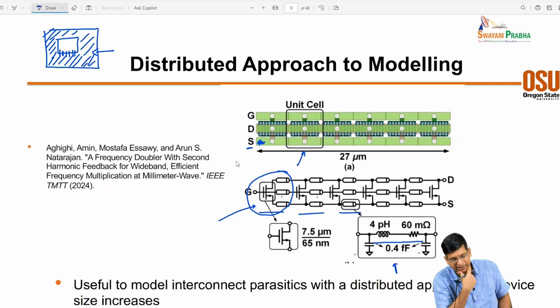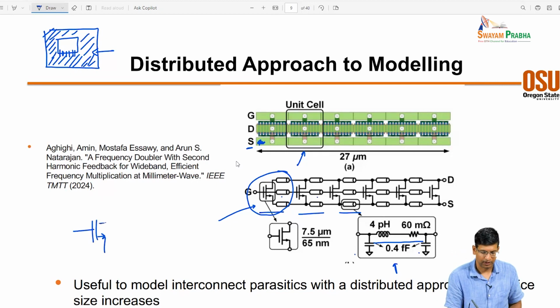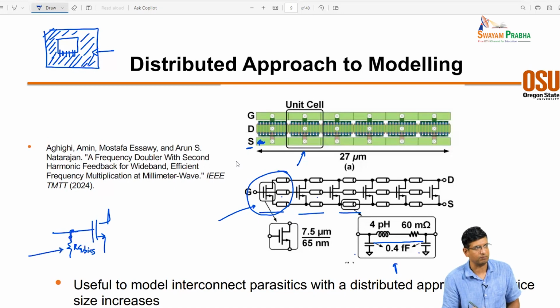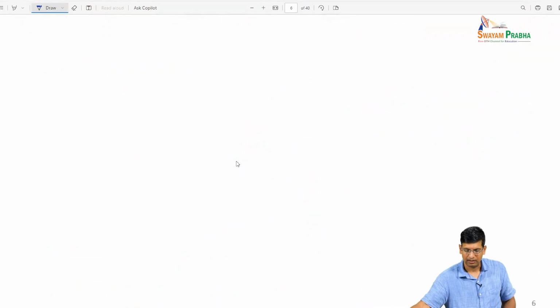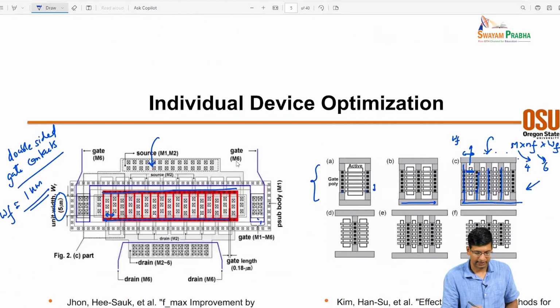Yeah. The biasing is typically taken separately, but it depends upon how you do the biasing. If you're biasing an amplifier, for example, where you have a gate coming in like this, a gate bias, then this resistance doesn't really matter for you. So you do all of this in the lower metal layers. You never bring up that bias contact. It is going to go into the gate right at M1 or something like that. You'll just make the contact over here.